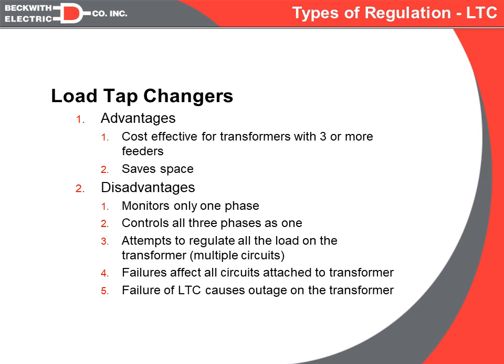And if not, we're going to have to do downline correction to make it look the same. So if we have 4 feeders, we want each of the 4 feeders to have approximately the same voltage drop. If we have one feeder with a 4 volt drop and another feeder with a 10 volt drop, we're going to have issues.